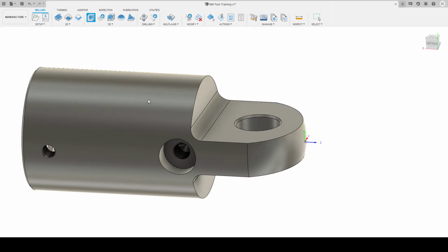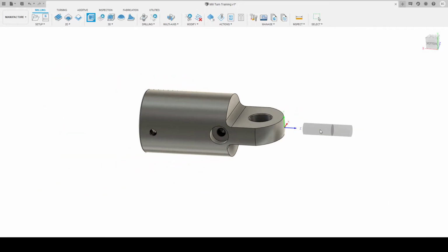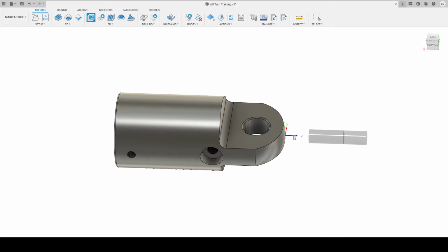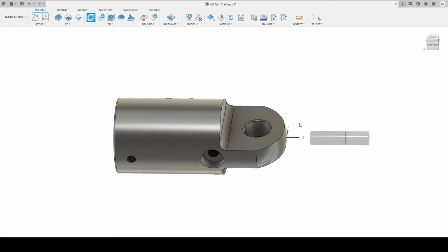Again, you won't need to do the feeds and speeds because I'll create the tool libraries for you. So we'll just go fairly conservative here. Very good, and we'll call this one tool 3. Every different tool we have is unique with a unique tool number. Alright, so we can click accept on that. We can select our tool, and we'll see it's brought our tool out, but it's actually facing the wrong orientation. We can fix that by going into our geometry tab and tool orientation button.